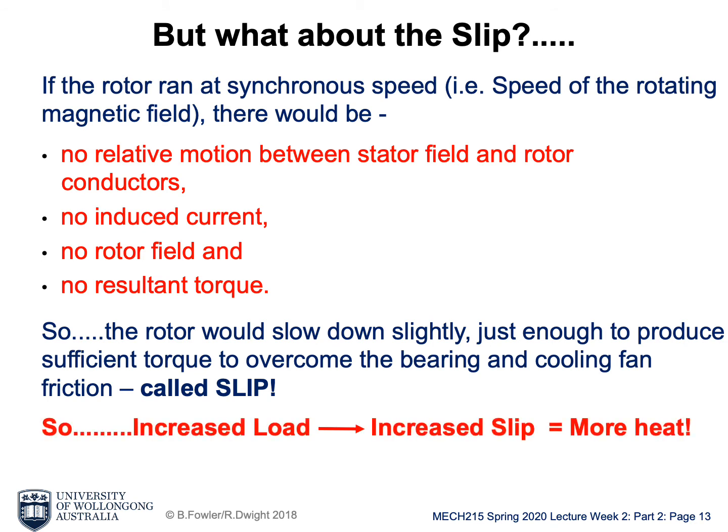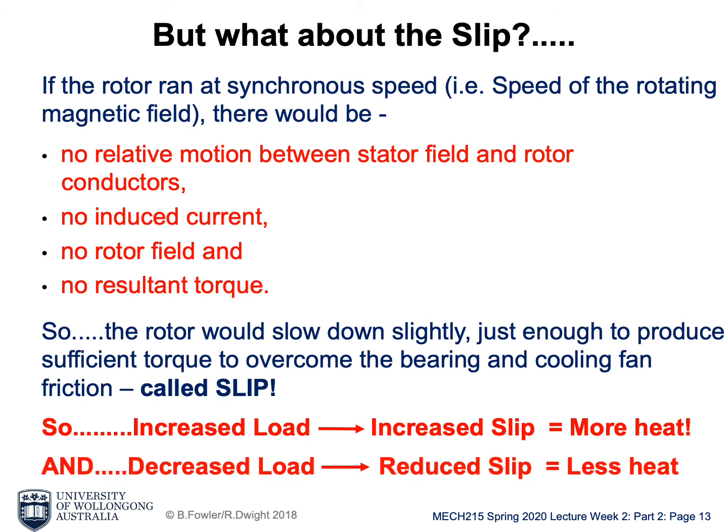If we increase the load, the rotor will slow down a little bit, which increases the slip and generates more heat. If we decrease the load, the slip will be reduced, and there will be less heat. Normally the slip is about 4% for this induction motor.